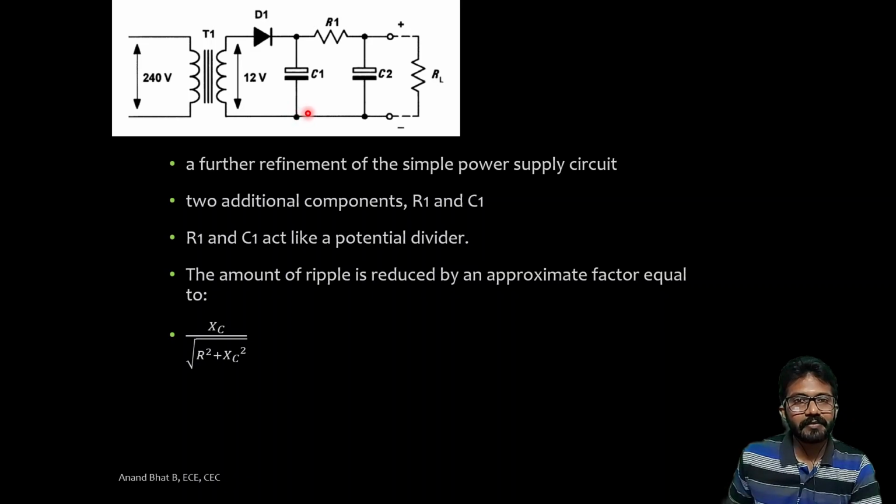It indicates that we can add as many capacitors as we want in order to get smoother and smoother waveforms, but like I said, it comes with added cost, and the added cost is that the capacitor requires energy to charge and it will be drawn from the supply. So for a very small instant of time for the capacitors to charge, a very large value of current will be drawn from the supply, which is not acceptable. It causes surges and thus it may damage the transformer also. So a maximum of 2 capacitors can be allowed in practical circuits.